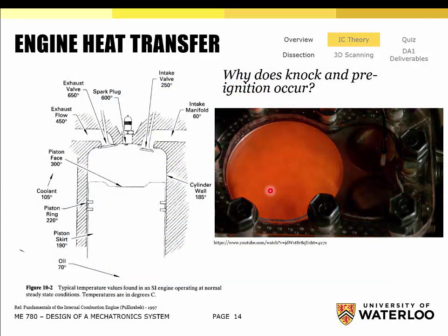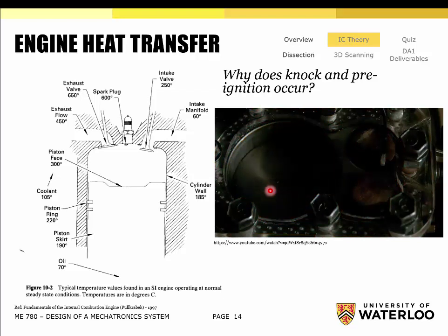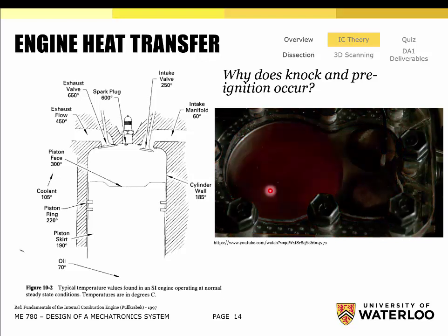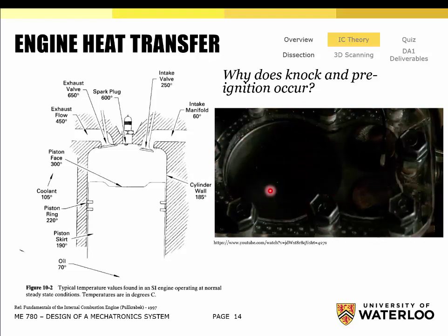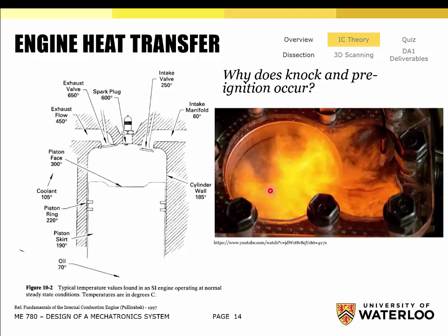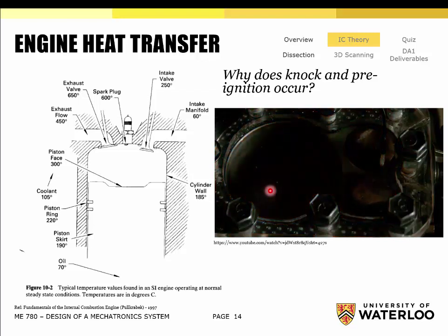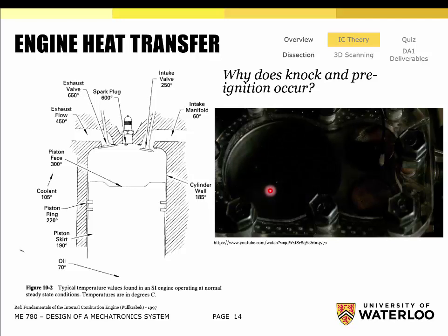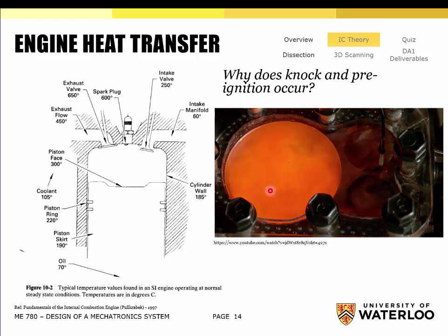Okay, so which valve is open when the exhaust is traveling out? It's the lower one, yes. So you can see it's ignited there, the piston is moving down, it's producing usable work, and the lower one here is open, and you actually don't see the flames going out because it's fully burnt. That's good, okay? The flames are only occurring as the combustion event is sweeping the combustion chamber and pushing down on the cylinder. You can actually see small little fuel droplets coming in the intake side here before the spark